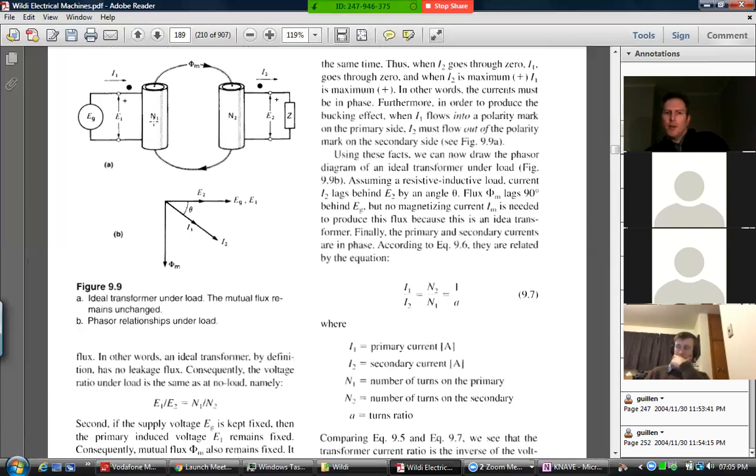So there is a little bit of current required, but in the perfect ideal transformer, that current approaches 0. In other words, it needs a very tiny amount of current if you've got a very easy magnetic path, very, very low reluctance. But in reality, you've got to take a significant amount of current to actually get some flux in that magnetic circuit. But it's still only a few percent compared to the current that flows under full load.